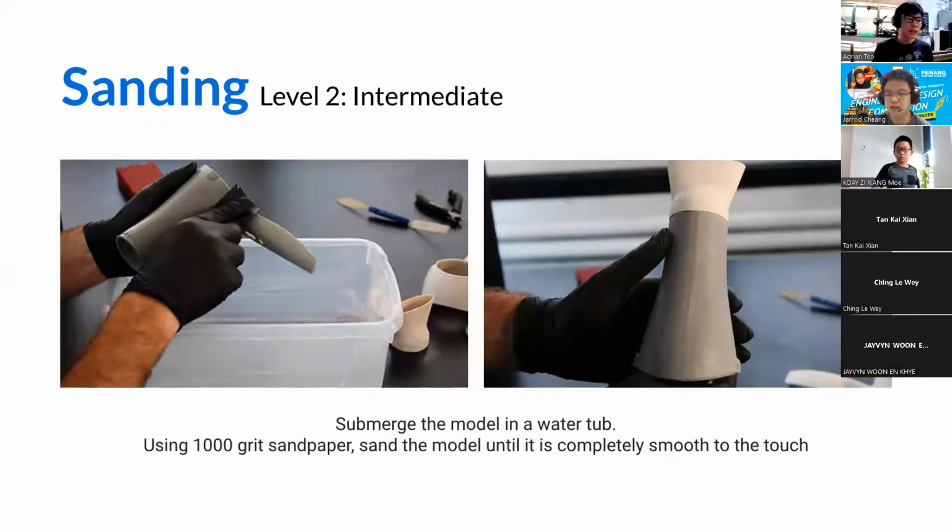Okay, so you need to dry it. You can wipe it with a dry cloth and then you can leave it under the sun. No, we are dealing with PLA material, so don't leave it under the sun. You will melt your 3D printed part. So bear in mind that most of you are printing with PLA. Don't dry your print under the sun because it's going to melt your print. Okay, use a hair dryer, cold air and blow it, or put it under a fan and slowly blow and dry it. Okay, cold dry it, don't hot dry it. Okay.